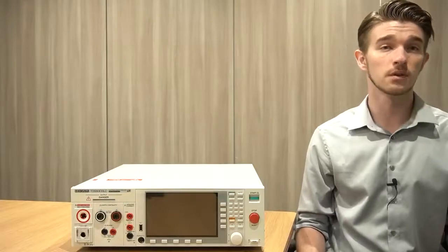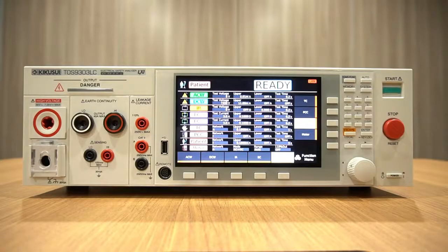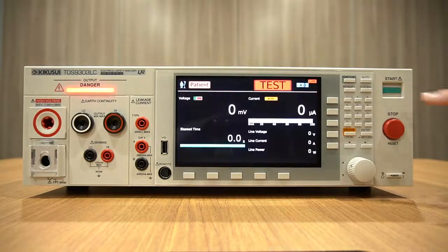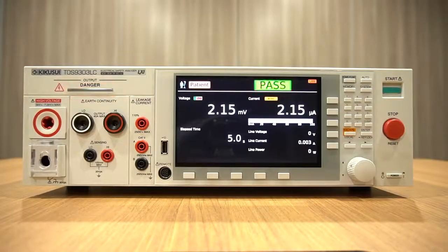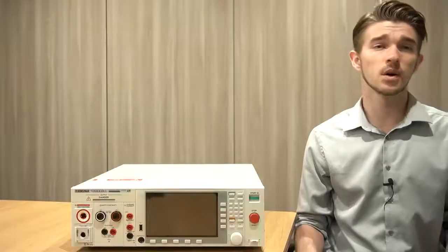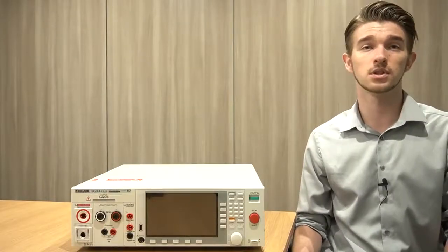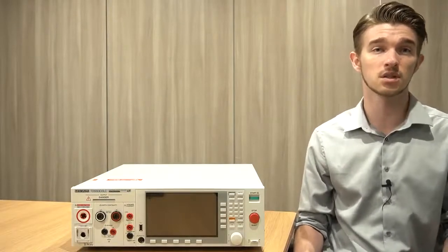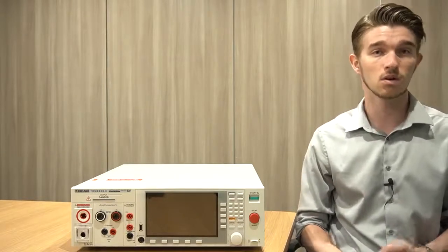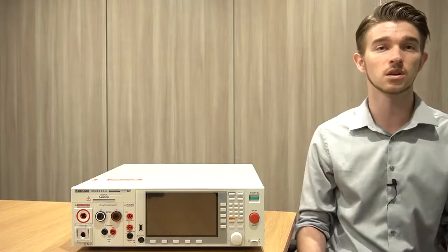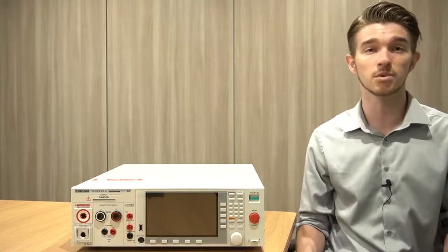All you need to do is make sure that Ready is shown on the display, and then press Start. You can monitor the test progress while it is being conducted until a proper judgment has been made. The TOS9300 will notify if your DUT performed within specifications with a pass judgment, or will give you either an L fail or a U fail if the leakage current went either above or below the upper and lower current